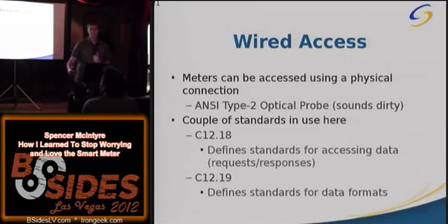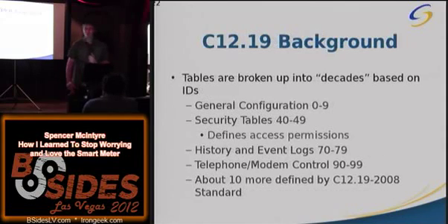There's also additional standards that determine how the information can be accessed over modem connections. I believe that's C12.21 or it might be 22, but those are going over modem connections, like telephone connections. All right, so C12.18 is pretty simple, so I'm actually going to skip over that. It's very much just dictating the codes for responses and requests for how we can actually discuss information with the device and pull information back out.